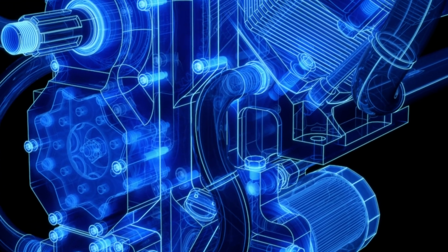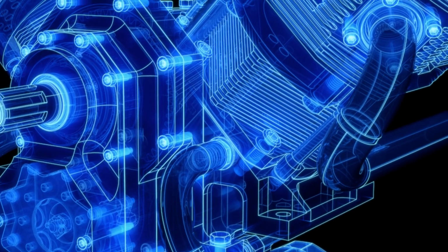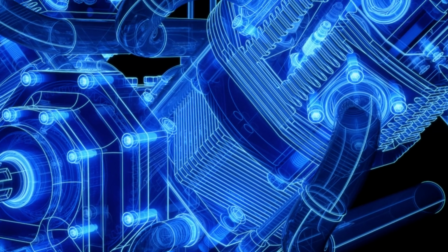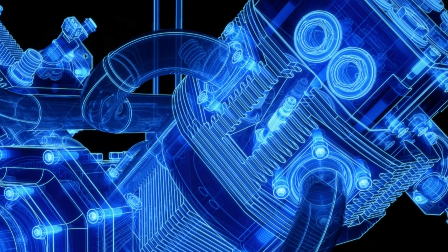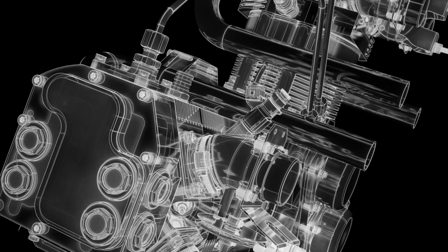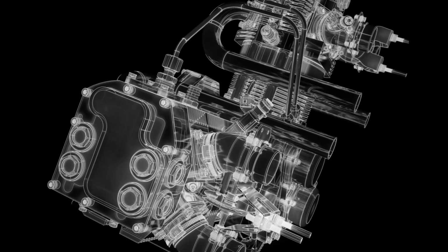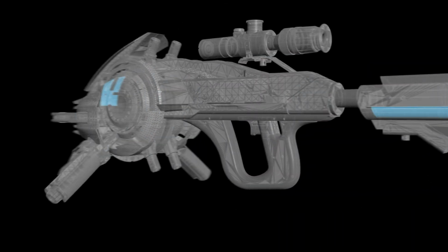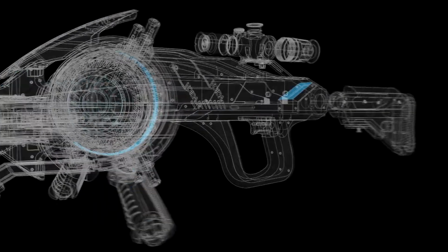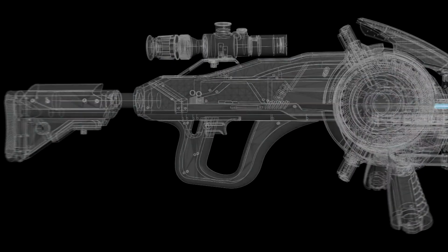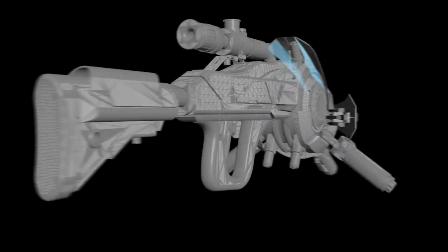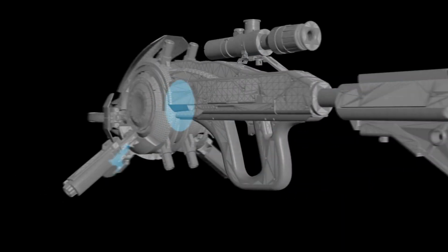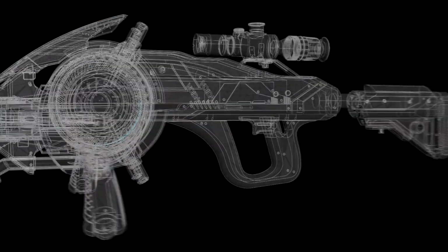In this video, we're gonna learn how to recreate wireframe from CAD data. We're gonna use Moment of Inspiration to create the mesh, and then we're gonna build a little process in Houdini to recreate a wireframe around all the patches, and also create true real geometry for the wireframe, so you can render it in any render engine of your choice.